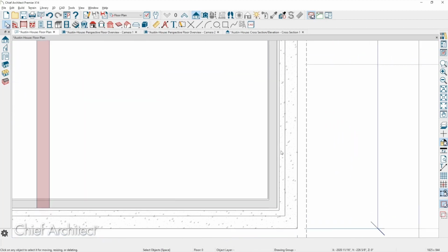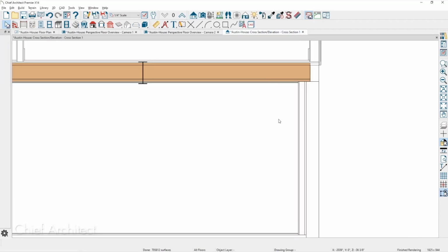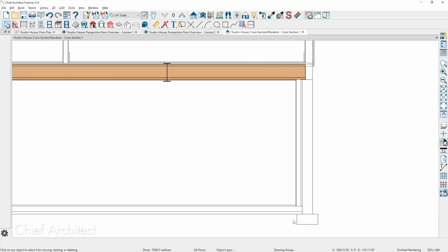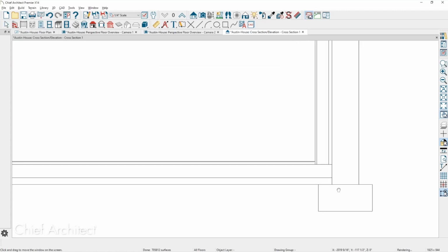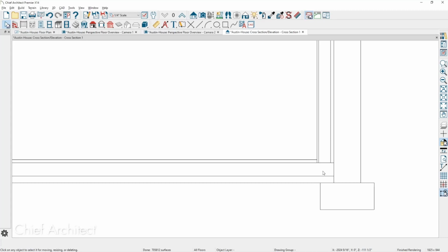As we zoom in a little bit closer, it is exactly as you might build it for a foundation and a basement that's enclosed with those furred framed walls. And you're going to get a better structure connection, because sometimes if you build it as one single wall, my footing extends down, and I probably could make a bigger footing to support that, but that wall may extend down into the footing. If it's a singular wall, the platform probably wouldn't build quite the way I'd want it. So I usually use a separate wall, a little bit more work, but it is structurally more accurate when you cut your sections. Agreed. Thank you.